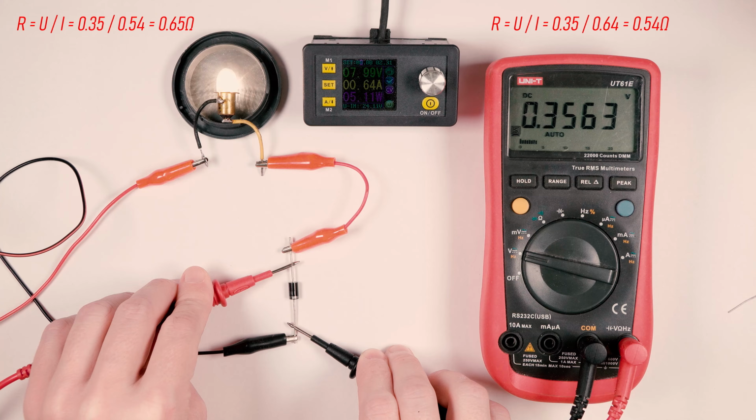This happens because the diode is a semiconductor device with a nonlinear VI characteristic. As the current increases, it reduces its resistance in order to keep the drop at the same level. Since for a particular diode, the drop value is basically unchanged, it is one of its main characteristics. That is why when measuring diodes, the multimeter displays voltage drop rather than resistance.